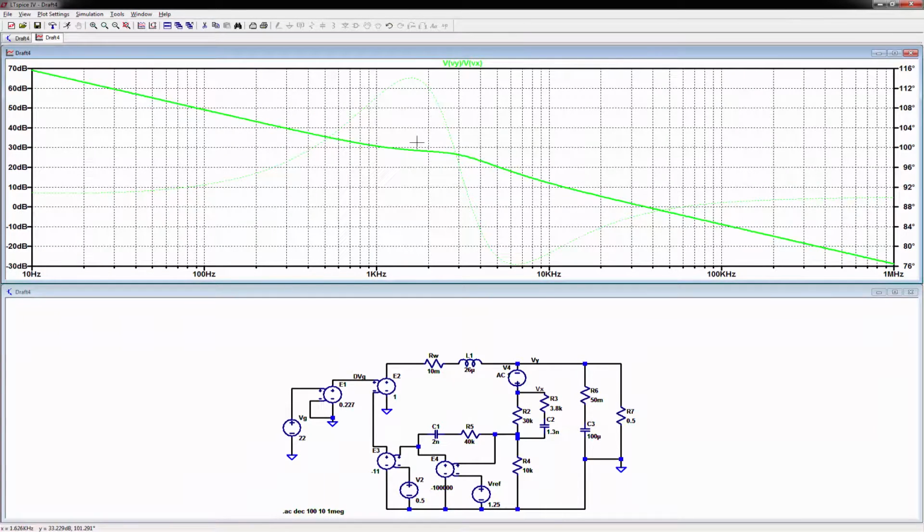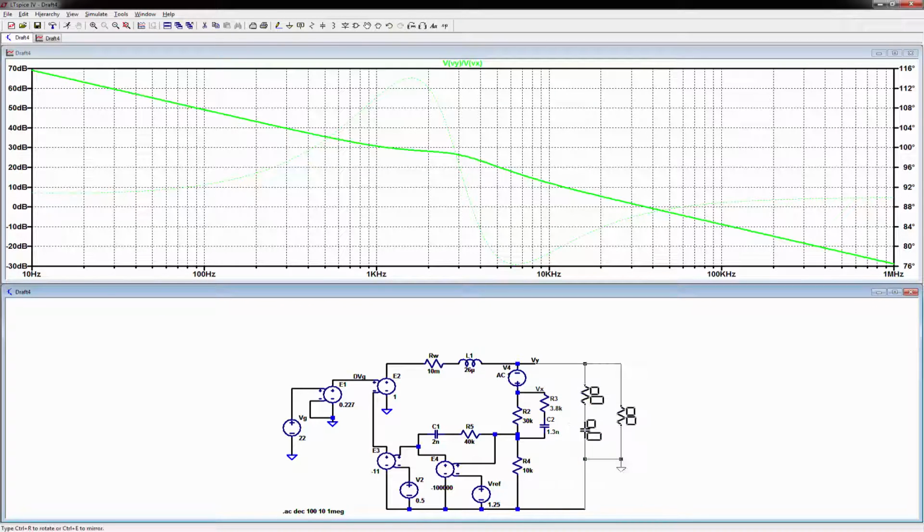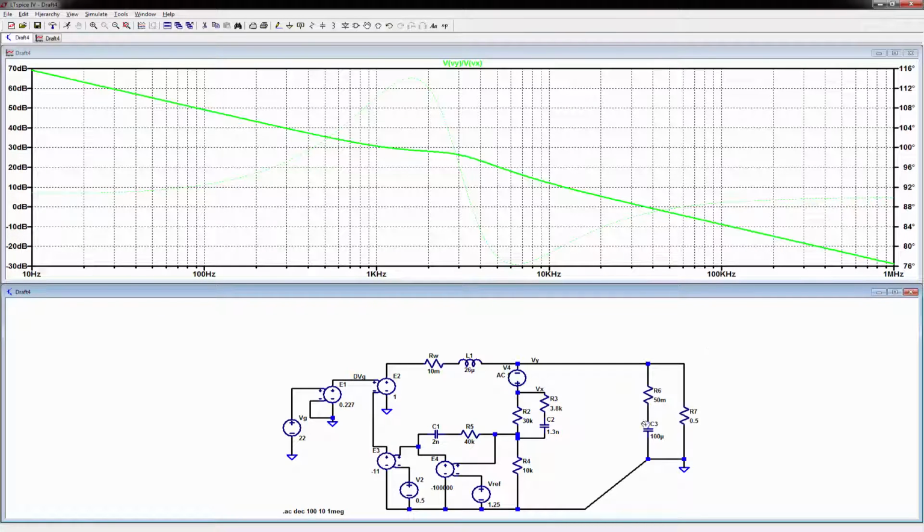So what we need to do is get rid of this Q. And remember, how you get rid of the Q is you de-Q the circuit. So we come back into our circuit, just like we did before. We open this up, move this out a little. And then we're going to add in this, I'll just copy these two, which makes it fast.